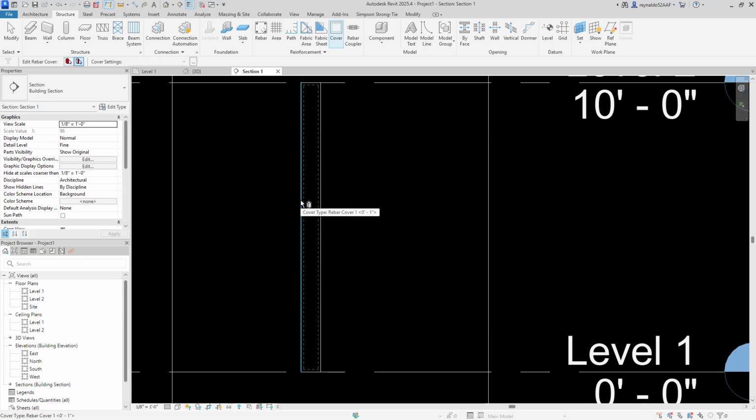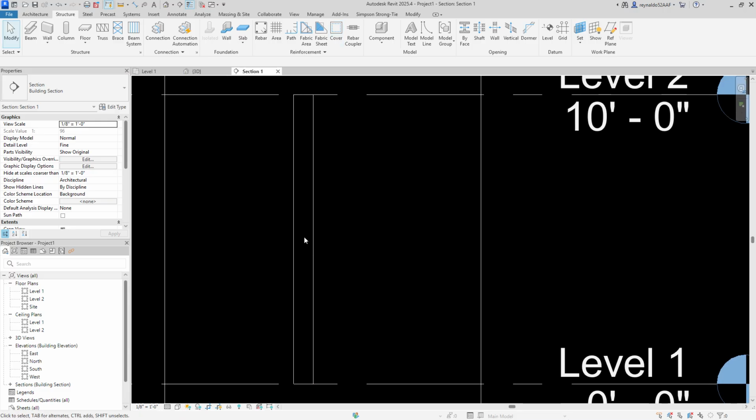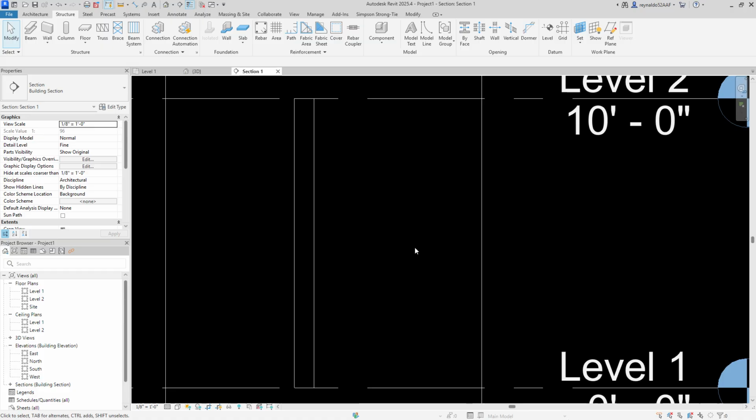We'll click on that side wall, activates the offset. We'll go to our drop down menu and we'll choose 1.5 inches since it's a wall, and then we'll choose 1.5 inches there, and then from the bottom we'll click the bottom and we'll change that to 1.5 inches offset, just like that. So now that the offsets are set up, then you would go about setting your rebar.